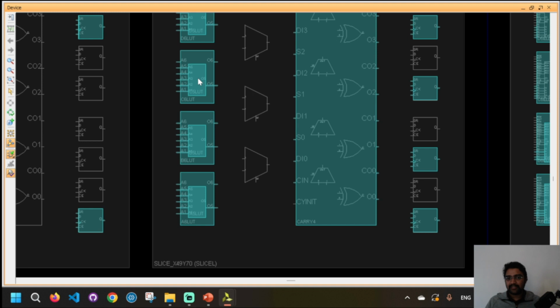Now lookup tables are inputs for all these logic cells. So what are lookup tables again? Those are the set of data inputs, like truth tables, like tables of information. When you set some instruction, all this data will be going to these lookup tables, and then the lookup table will process it towards these logic cells. You can see it is using FPGA native LUT6_2 type lookup tables.